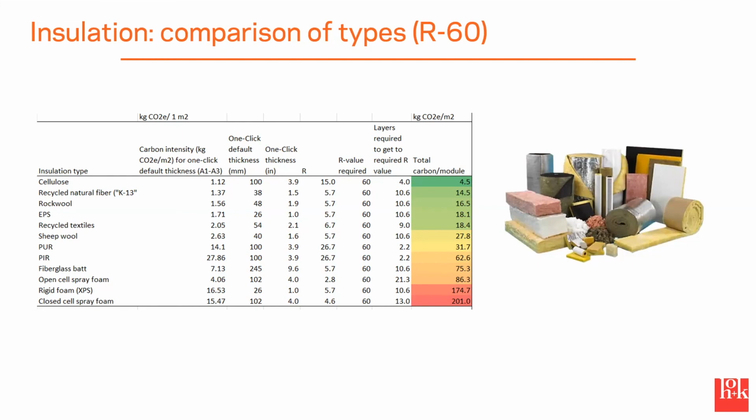You guys talked about carbon quite a bit too. I know for University of Michigan, we were contemplating trying to use CarbonCure. How does that stack up against fly ash? Yeah, that's a great question, Tony. It's about a 5 to 10% reduction, so it's equivalent to using a 10% fly ash mix.